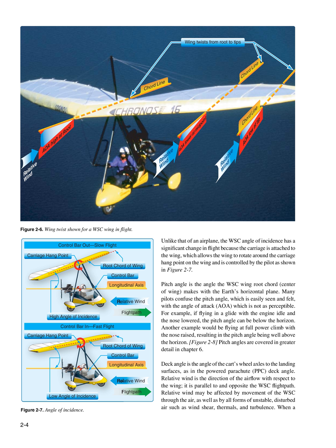Deck angle is the angle of the cart's wheel axles to the landing surfaces, as in the powered parachute, PPC deck angle. Relative wind is the direction of the airflow with respect to the wing. It is parallel to and opposite the WSC flight path. Relative wind may be affected by movement of the WSC through the air, as well as by all forms of unstable, disturbed air such as wind shear, thermals, and turbulence.